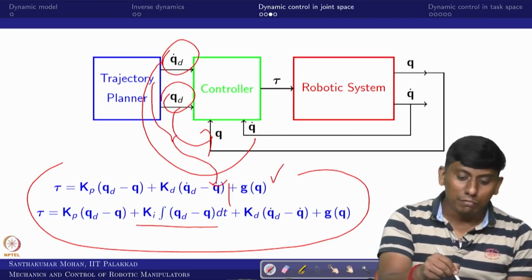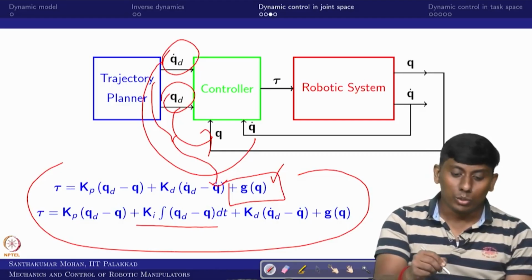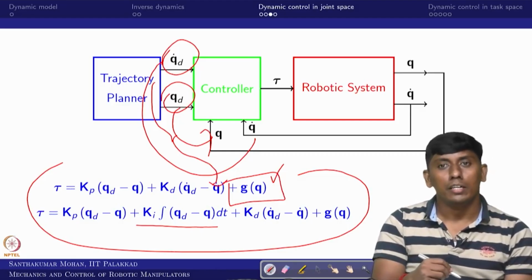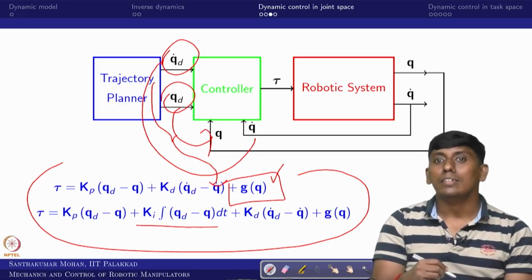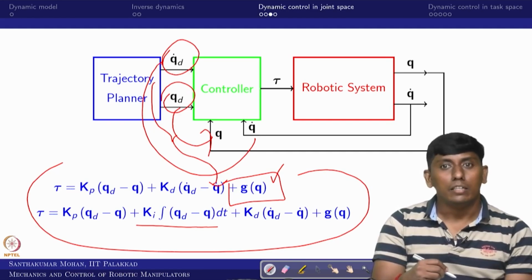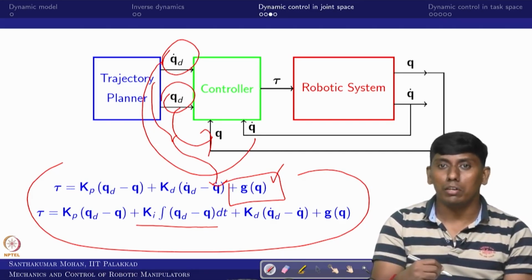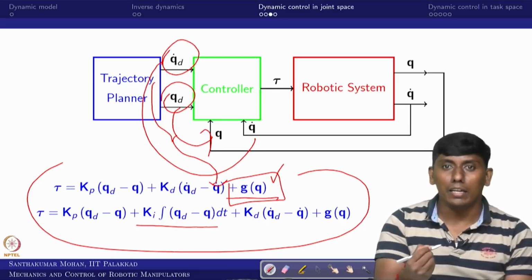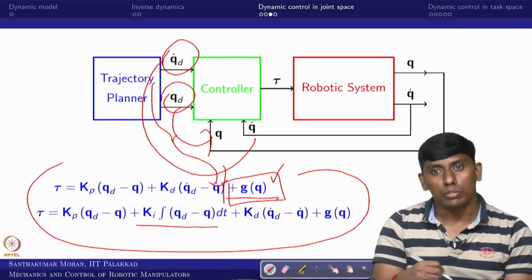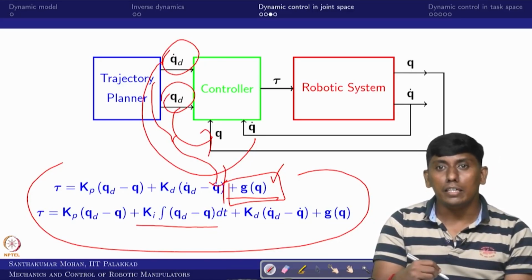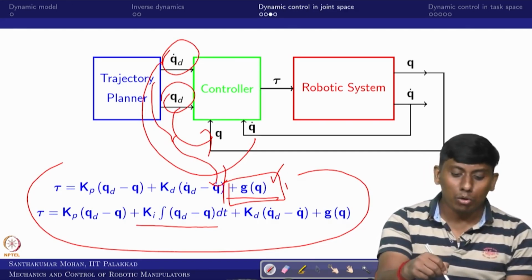Further, if the system is in a spatial configuration, the gravity also needs to be compensated, but most of the modern or even old manipulators are gravity balanced systems. Either spring based, or cable driven, or some kind of electrical actuation based. So the gravity is already balanced. In that case simple PD and PID can be used. Even in the industry, in a ready manipulator, the PD control would be used.